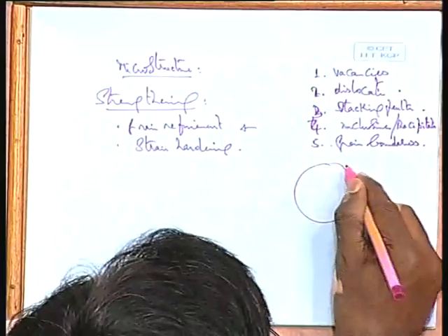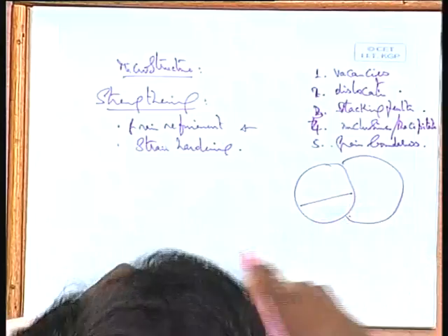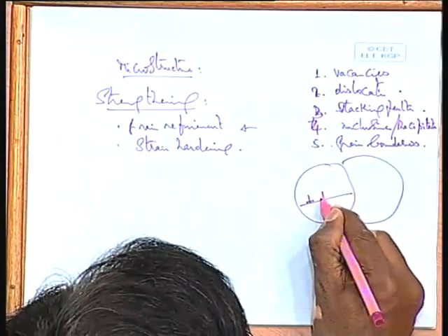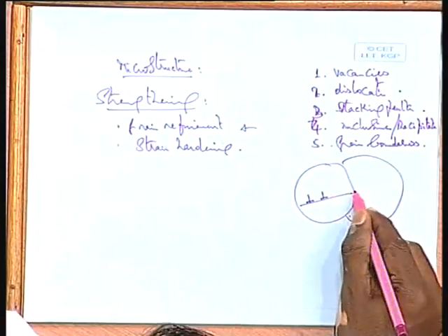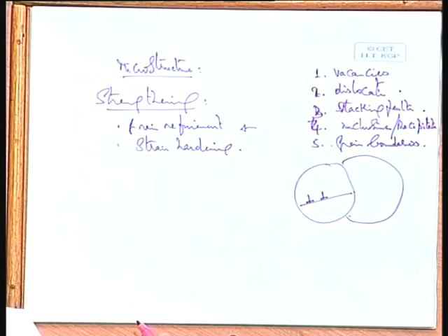Why does the grain boundary act as a barrier? Yes, it is because of the orientation. Imagine a dislocation moving on a slip plane in a particular direction. Imagine there are two grains, and you have a plane on which a dislocation is moving. The moment you come across a grain boundary, it means a discontinuity as far as that plane is concerned.